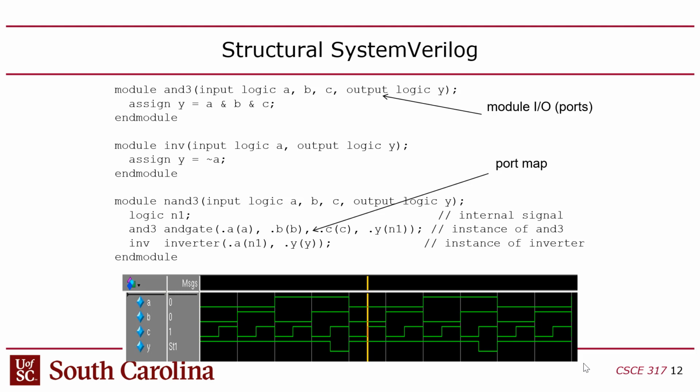And that's the number of samples it will record whenever a triggering event happens, and then those get offloaded over JTAG, which then operates subsequently over USB, and goes into your workstation, and then you can look at a view like this, but not of simulation results, but the actual signals as measured on the FPGA. It's not real time, of course, because you have to record the data and then offload it over USB. And USB isn't fast enough to measure signals at 50 megahertz.